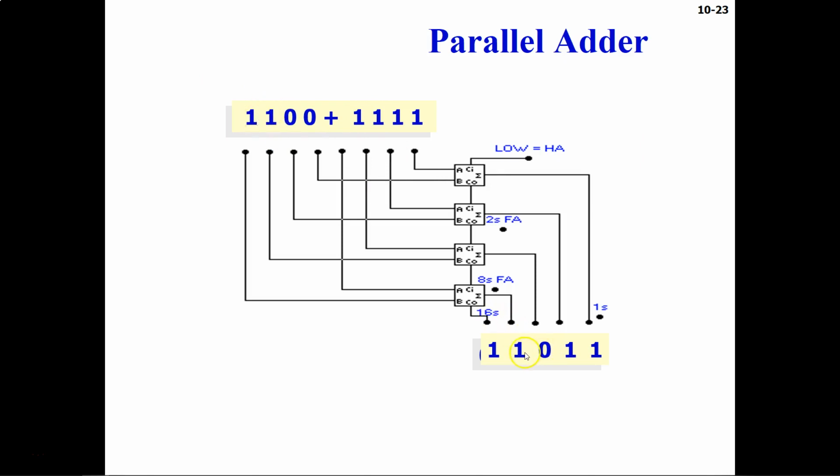So that's why you have 0 here and then 1 carry here, and then 1 plus 1 is again 2, which means 1 0, and then the carry will go to the other step, and the previous carry will add in up here. So that's why you have 1 here and then 1 here. So this is going to be the result, and again this is going to be your least significant bit, this is going to be your most significant bit.